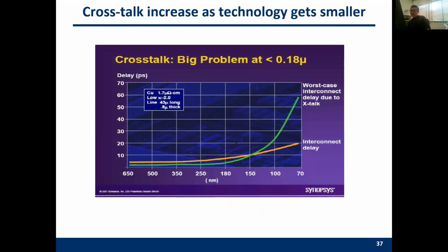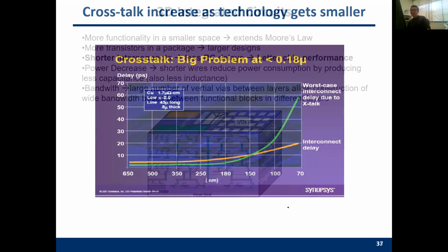Besides the larger power consumption and the slower speed of the current FPGA, we also have a lot of crosstalk problems. For example, if you have two parallel interconnections, signals may mess up here because of the crosstalk issue. You have different solutions. First, reduce the frequency, which can help you to improve the reliability. But nobody wants to do that because that will hurt your performance.